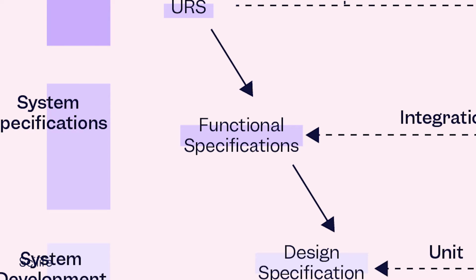A functional specification is a document that describes how a process or a system will operate. These functional specifications are written by the supplier after the URS are provided by the owner. It does not contain any highly technical detail. Rather, it describes how the system will operate according to the user requirement specifications. It also describes how people will interact with it and what to expect when different operational scenarios occur.